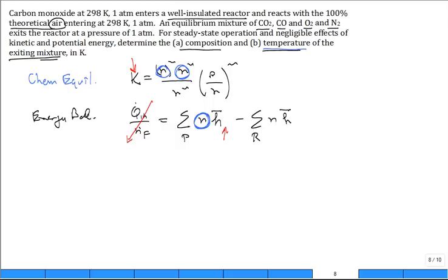So what you have to understand is you write down the reaction equation. So we're going to have carbon monoxide and air, O2 plus 3.76 N2. Goes to, let's write it down for complete combustion. So you would go to CO2, true? That's finishing the carbon balance. And then there's no hydrogen. What about the oxygen balance?